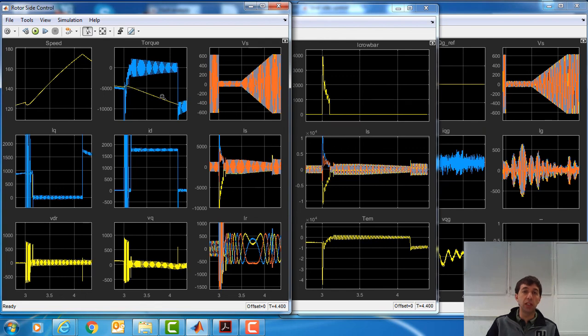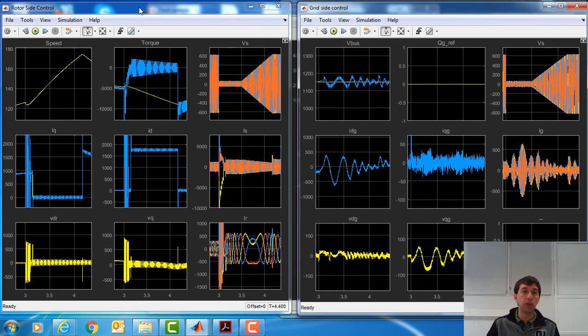As the reference is this one, given by the maximum power point tracking, we have lost control of the rotational speed, and we have had in this simulation this speed variation. In reality, we could have less variation because the inertia that we normally have is bigger than in this simulation that we have performed.